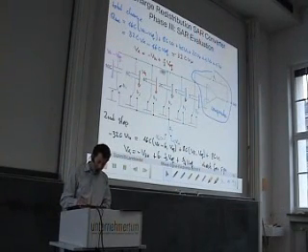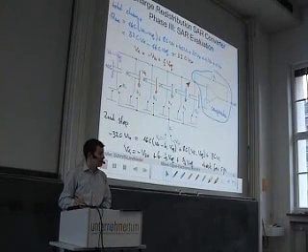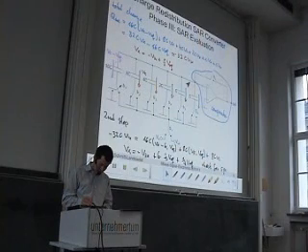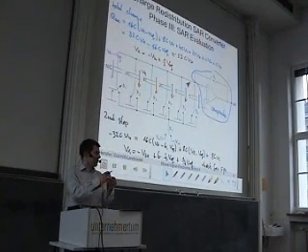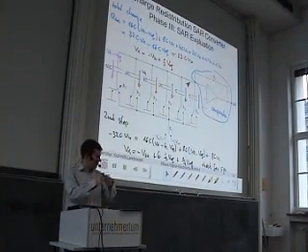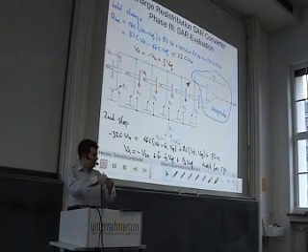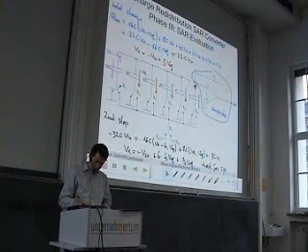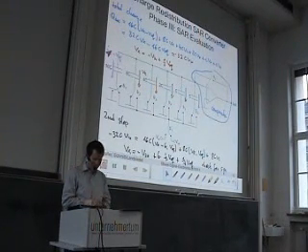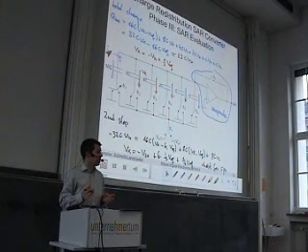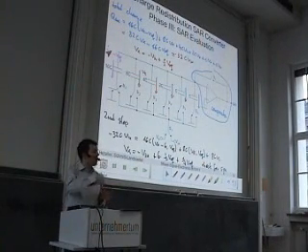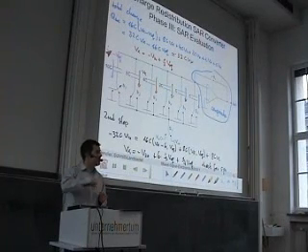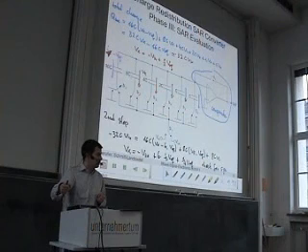Because the top node is completely isolated. So the question is, why can't the charge come from the Vref to the capacitors? Well, in a capacitor, if you place charge on one side, you also have to take it from the other side. And this common node for all these caps is isolated from the environment. So no charge can come out or go to this node. So any charge on one cap has to be placed on the others because it cannot leave this.